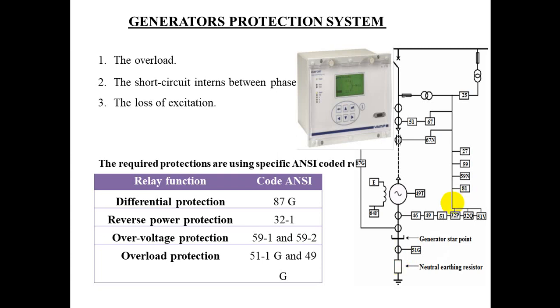Overspeed, flow devices, and temperature measuring devices for shaft bearing or stator winding, transformer winding, and transformer oil are non-trip type. For example, they only generate an alarm during abnormalities. But the other protective schemes ultimately operate the tripping relay of the generator.